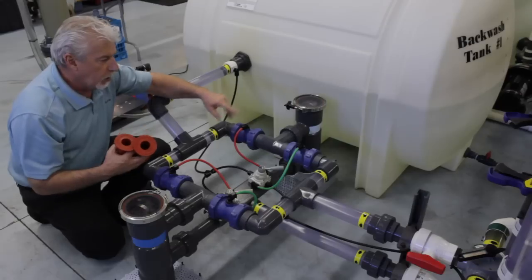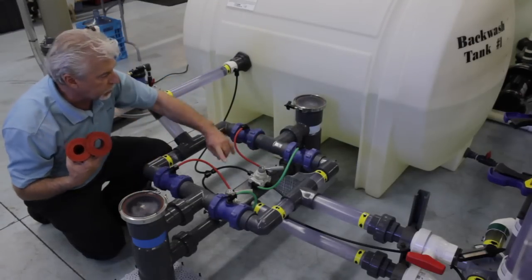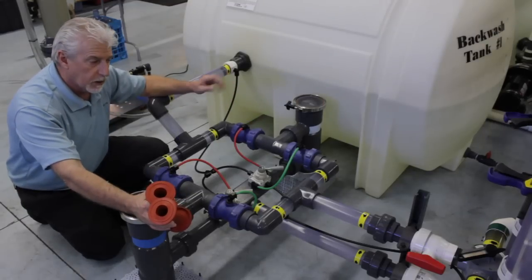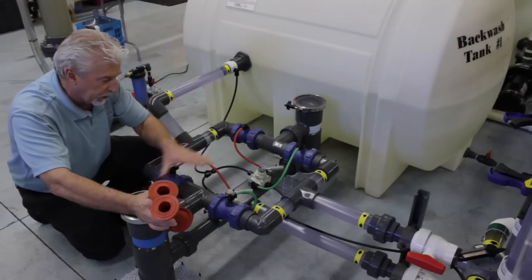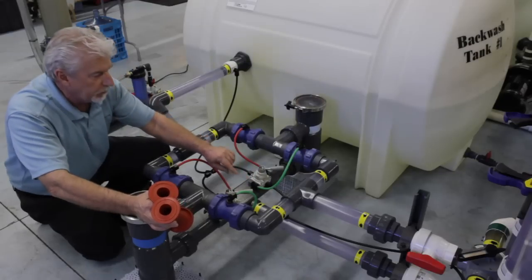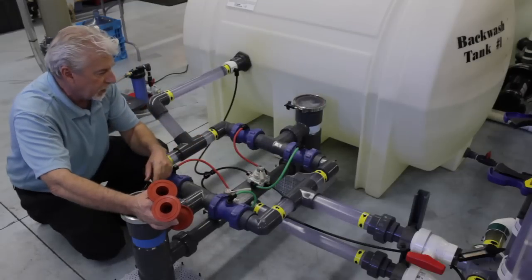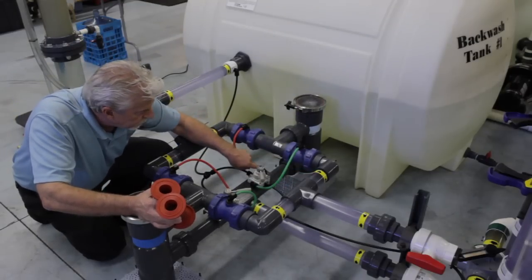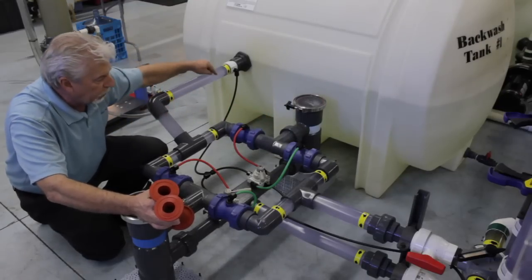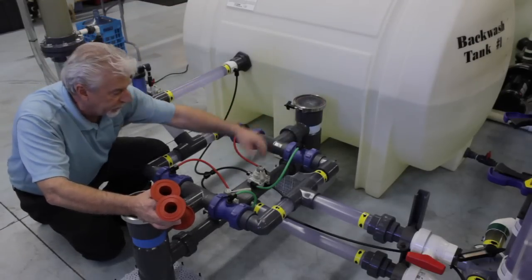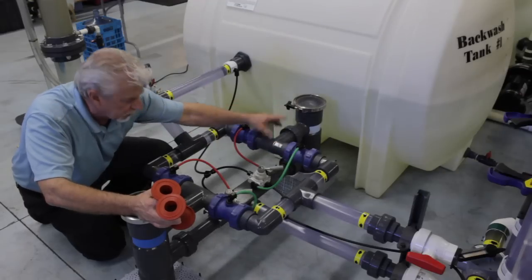Plus, remember, when I close this and open this, the clean water coming out of the one still online is actually doing the backwashing here. Back from scratch, water coming in, being split, going through both filters, being filtered, collected, back to the system. Time to backwash, close this, open this in one movement, just like that. Stops the flow here, takes clean water through the filter backwards, which would be a radial flow, sends it onto the waste. Quick pulse backwash, 15 seconds later, go back online. This is closed, this is open, everything's fine.